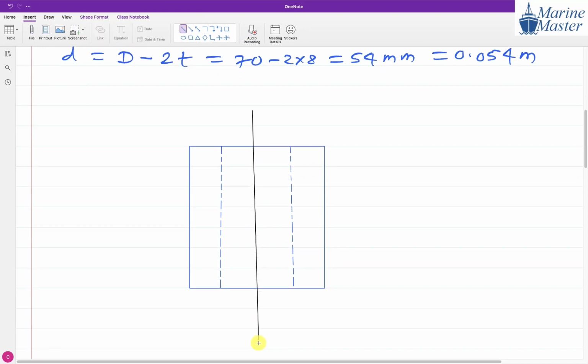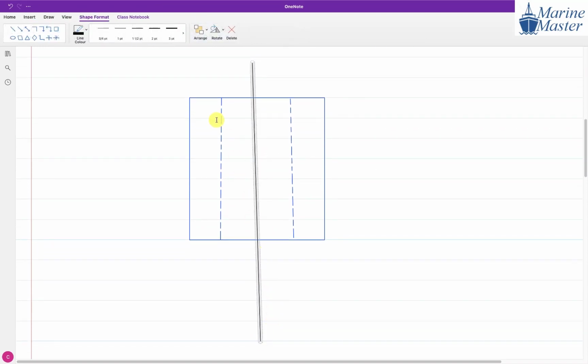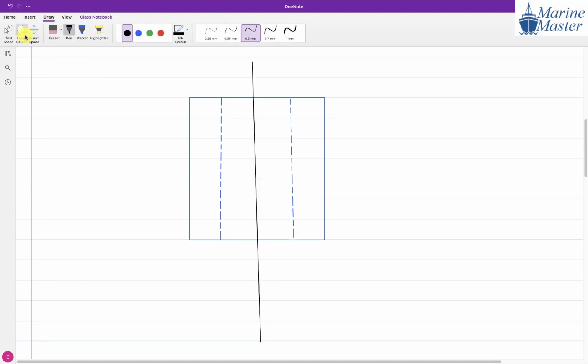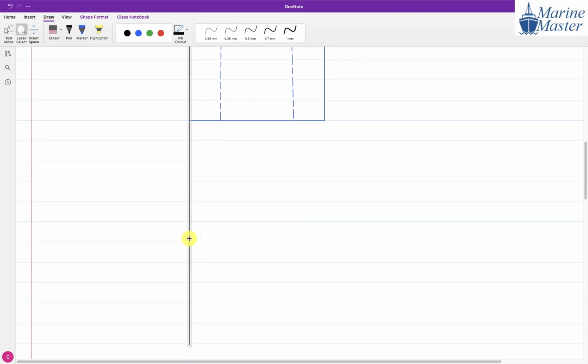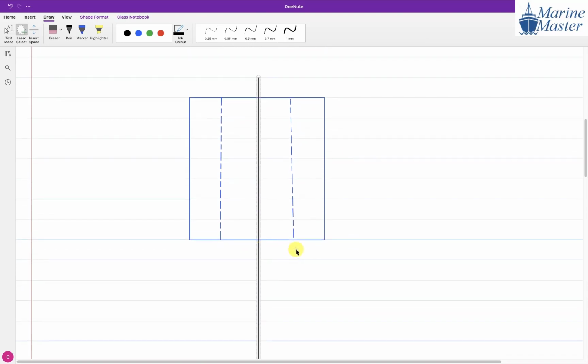The important thing will be the center line of the column. One minute, let me make it a properly vertical line. I will take it as a reference, and make it a proper vertical. So this is the center line. Now the next thing is the cross sectional area. How do we denote a center line? Bigger line, smaller line, then bigger line. Always follow the standard practice.